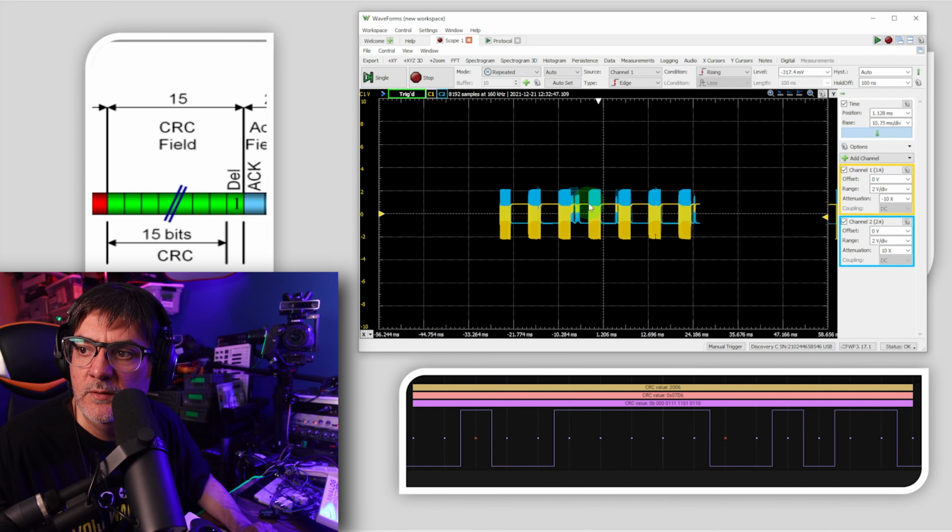It's too much for my brain to calculate the CRC, but there is a lot of documentation. Bosch has it, and I'm going to put it in the description too. And also there is some C or C++ code, so you can run the CRC, and this is an online check. The beauty of this protocol is that you can always have accurate information, and there are many ways to check for errors, which doesn't happen on FrSky. On FrSky, you lose a frame, something happened, boom, you're done.